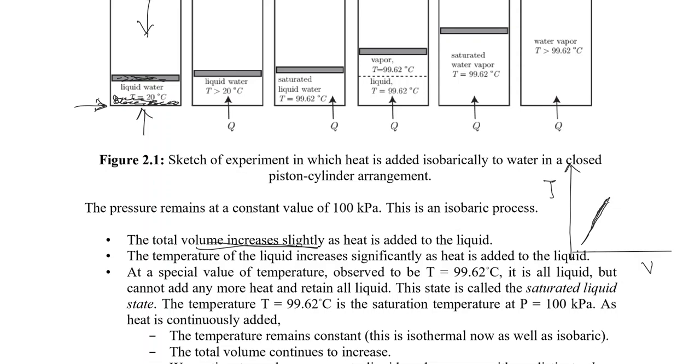Now, till when will it absorb the energy? Let me come back to this figure again. Energy is absorbed by one layer, then by another layer, and so on, until the whole body of molecules has absorbed enough energy. In other words, we would say the water is now saturated, saturated in terms of energy. Now if you supply more energy in terms of heat, there would be no temperature rise. So what would happen? The molecules at the top layer of the water will try to get the energy, try to escape, and try to change their phase.